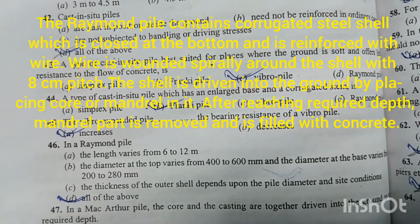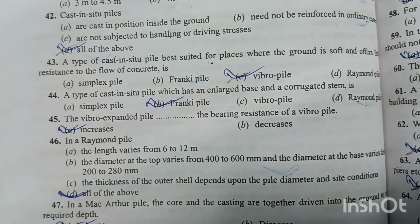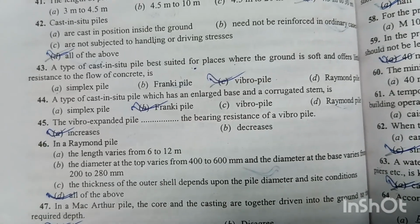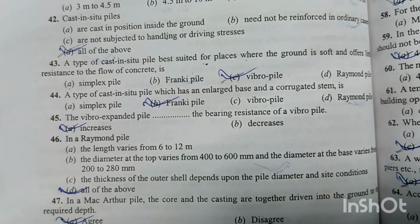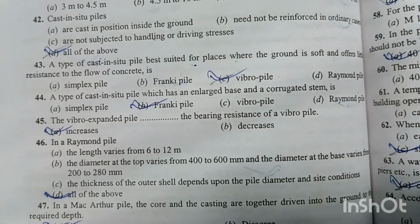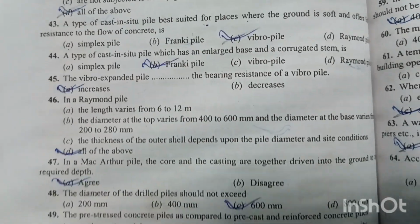Question number 46. In a Raymond pile, option A, the length varies from 6 to 12 meter. Right. Option B, the diameter at the top varies from 400 to 600 mm and the diameter at the base varies from 200 to 280 mm. Right. Option C, the thickness of the outer shell depends upon the pile diameter and the site condition. Right. Option D is the right answer, all of the above. Question number 47.